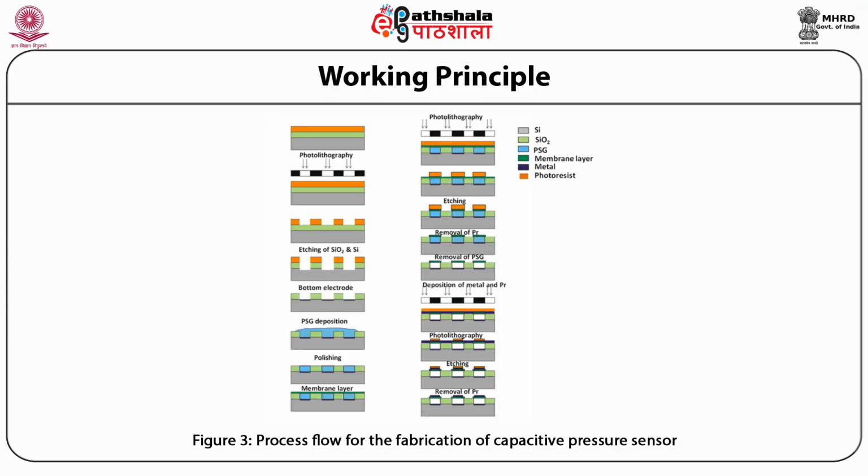After this step, the etching of SiO2 has been carried out on the Si wafer such that the grooves become deeper in the areas where there is no photoresist. After the formation of grooves, the layer over SiO2, that is the photoresist, is removed.